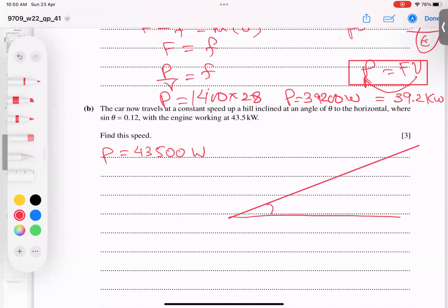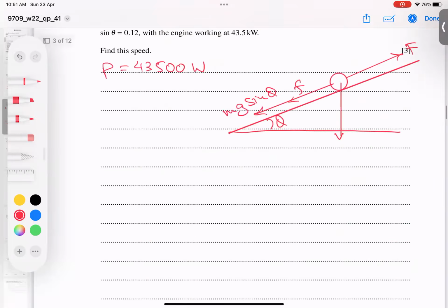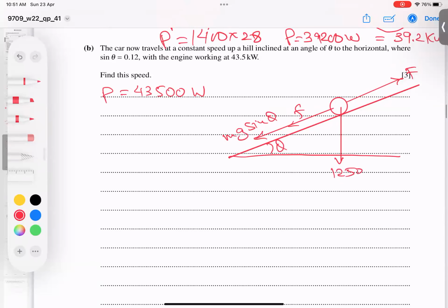So the inclined plane, I'm going to make it. Now this theta, and naturally when the particle is going up, this is called the applied force. So the applied force, and backward we have two forces acting, frictional force and mg sine theta, because the weight is mass m, and this mass is actually how much? 1250, into 10. So I should write it not as mg here. Now I'm writing directly 12500 sine theta, and the sine theta value is 0.1. I can replace it later on.